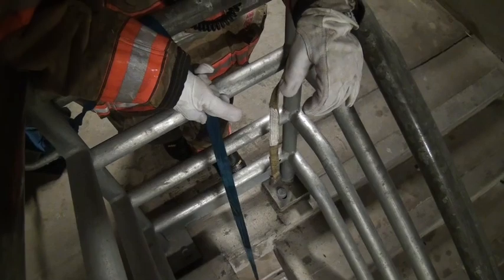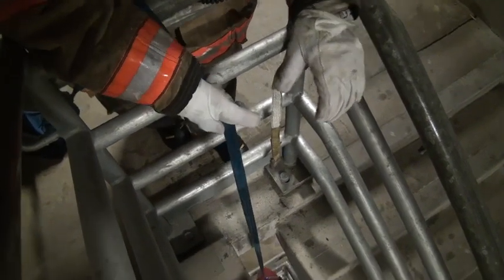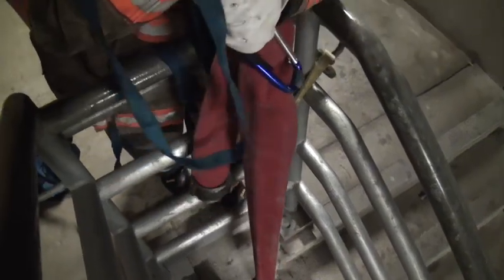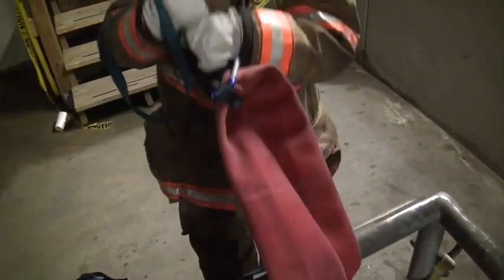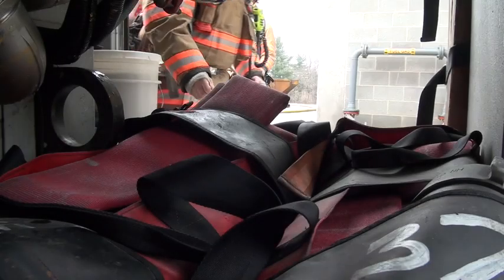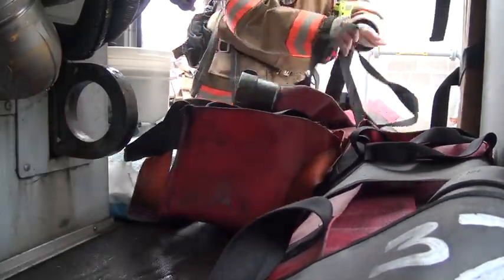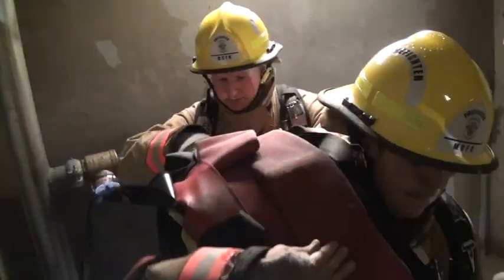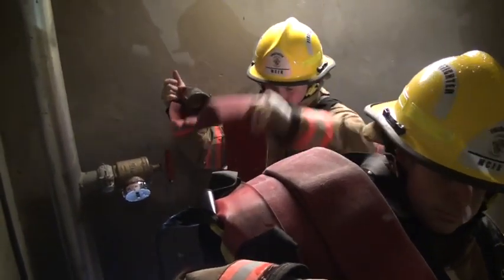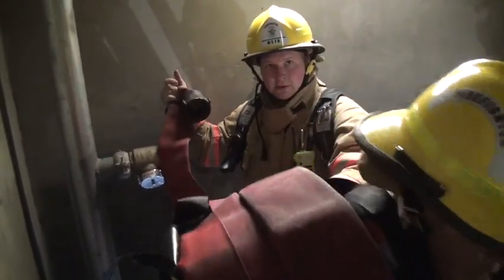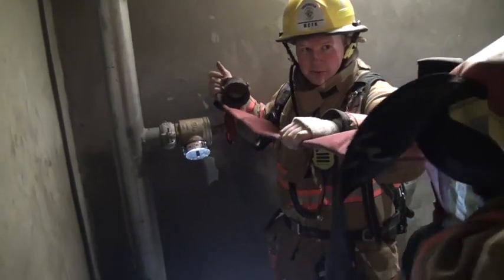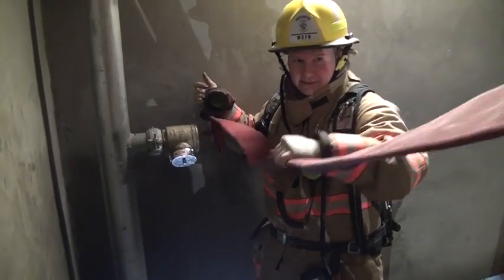Crews should train and practice on methods for overcoming a standpipe system being out of service. Hoisting a hose line up a stairwell. Operations on tight landings and in crowded stairwells are but a few suggestions. In cases where more gallons per minute are needed, the deployment of a 2.5-inch standpipe pack should be considered. As you can see, the deployment steps are the same, except the hose line is connected directly to the riser.